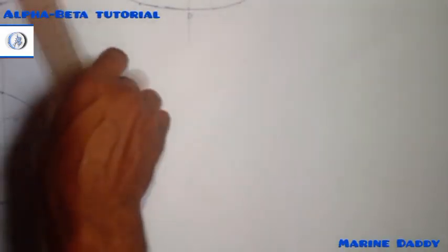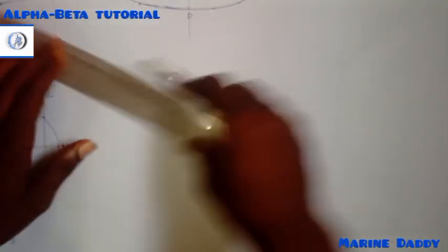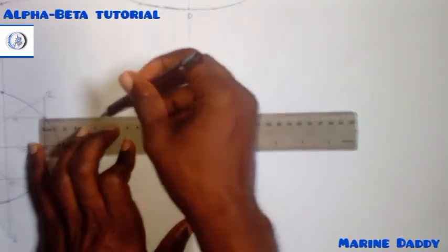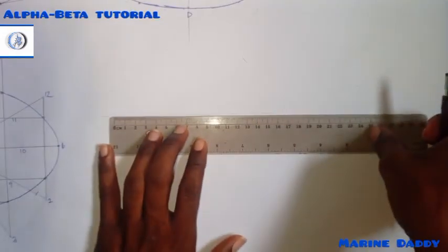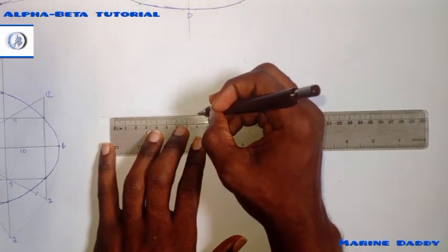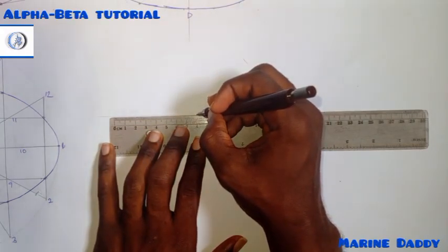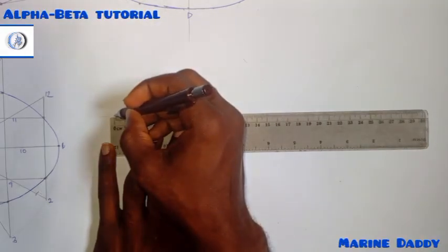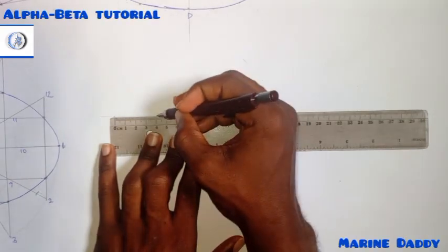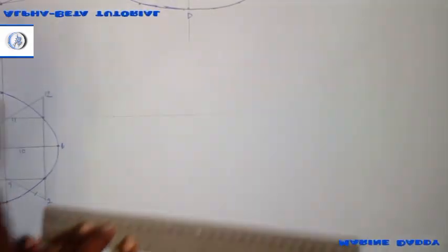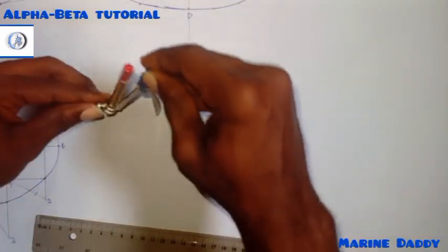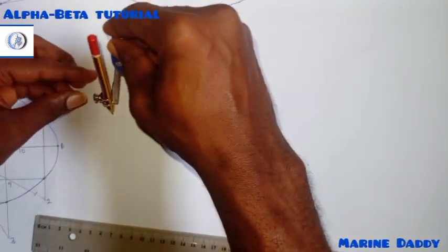Okay, how do we go about that? Still the same process. At the start, draw a fence line. So I've drawn my fence line. So there, get your distance across corners. They say distance across corners is 8. So from there, get your radius. Radius should be 4. Use it to draw your circle, a complete circle. Placing it like this.